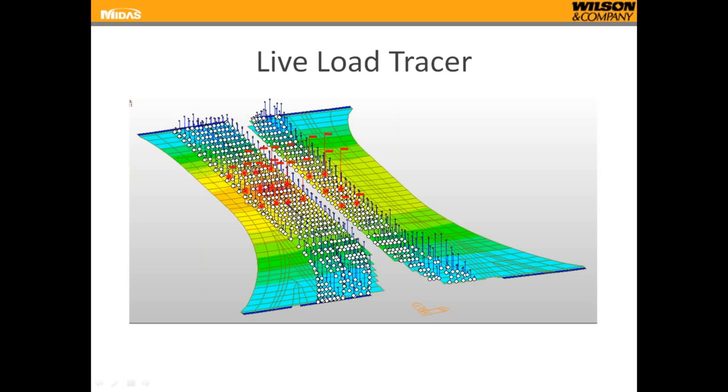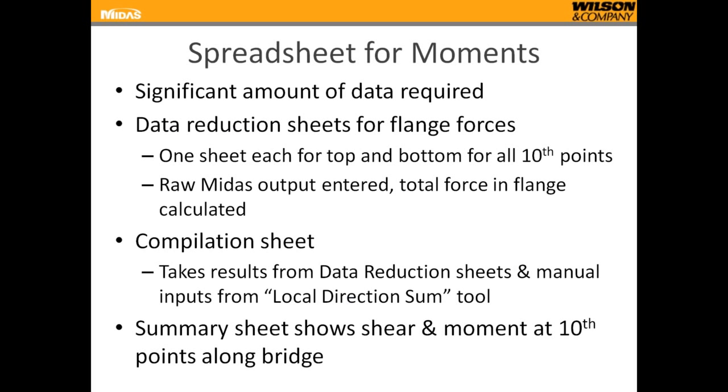Midas gives it as a text file, which can later be input as a load case. So if I'm trying to maximize moment in the web that sits under here, and I found that this was the controlling truck location, I could export these loads and then import it again as a load case and use that to calculate the moment and shear.